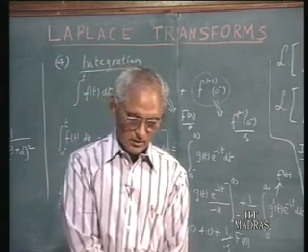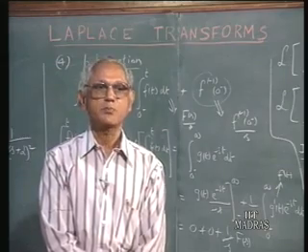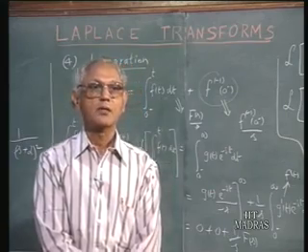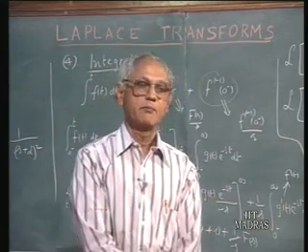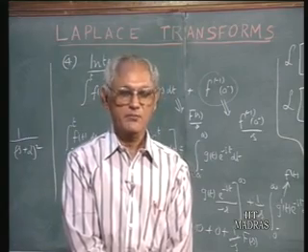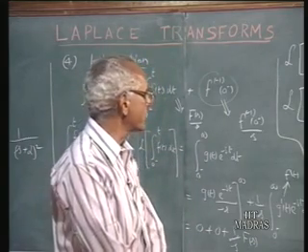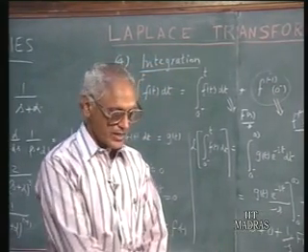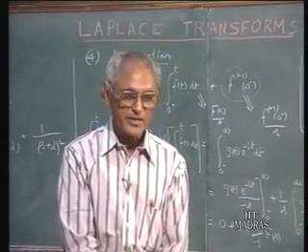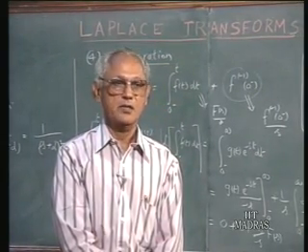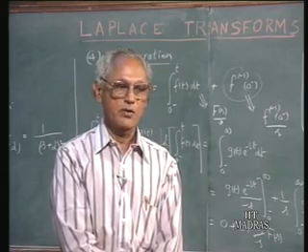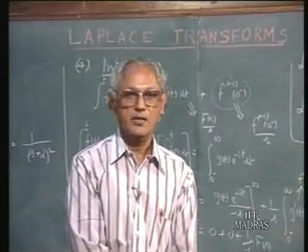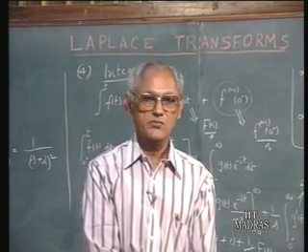Then we discussed how multiplication of f of t by various powers of t is transformed in the Laplace transform domain. In particular, we said t f(t) has a Laplace transform minus d by ds of F of s. Then we went to the integration of time functions, and we distinguished between the definite integral and the indefinite integral, and in both the derivative case and the integral case we saw how they can be applied to the situation of an inductor and a capacitor, how the relation between the transformed variables of currents and voltages across inductors and capacitors can be represented by means of such diagrams, which we called transform diagrams. We will continue the discussion of the properties of Laplace transforms in the next lecture.